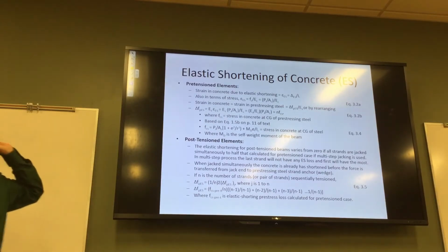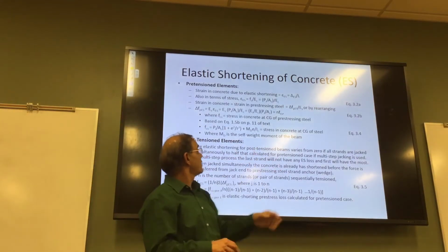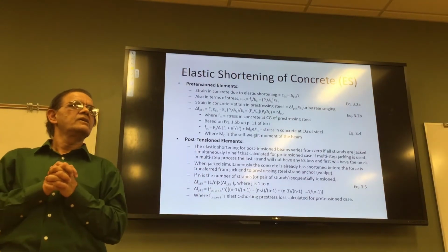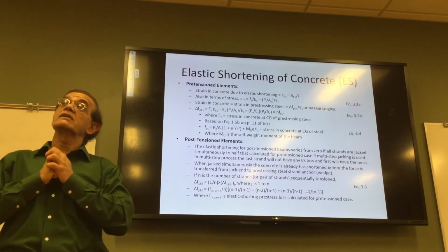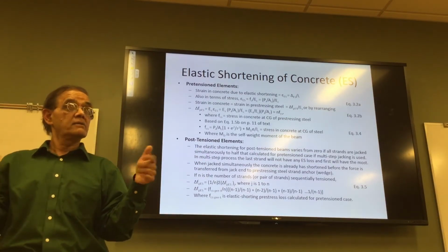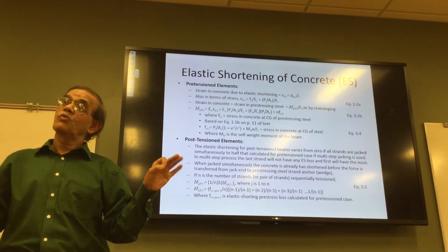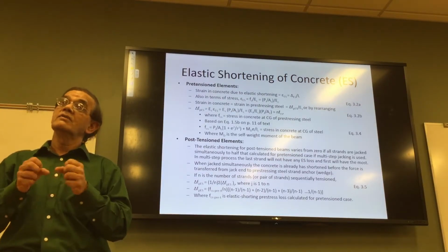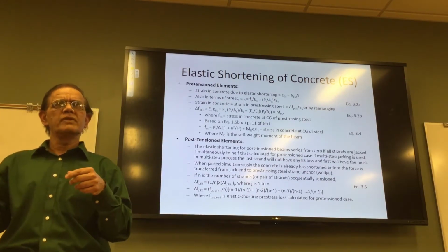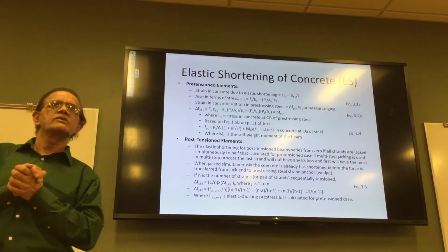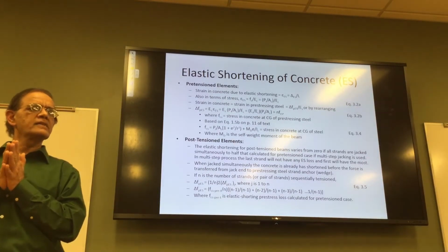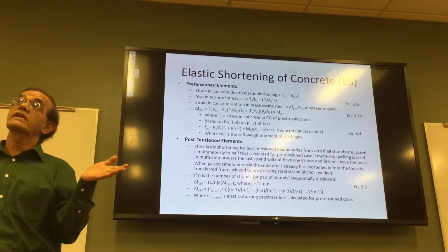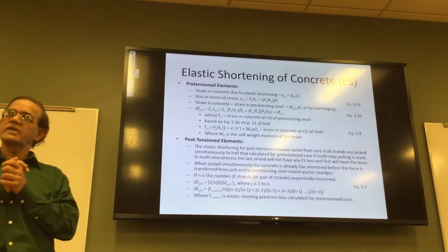Is it a standard value? No, it depends. It's not standard because even though the elastic modulus of steel is pretty much constant, you will see slight variation because the strands are braided, right? The wires are not braided, so the wires are pure. The braided wires or strands are not pure. When you stretch them, they're a little bit softer because they have been braided. They're not straight, right? That's why Es for strand is 27 times 10 to the power 6, and Es for wire and other things is 29. So there is a slight difference because of the shape, right?